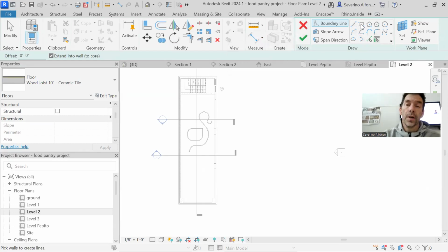But the drawing items, by the way, when you start a wall, when you start a floor, when you insert the door, the whole top bar changes, and it's a little bit confusing sometimes. What did you change my set of tools? Yes, I changed it. And at the beginning, you get a little annoyed, like, why are you doing that? Where am I? So just think of an editing mode or creation mode. It lives in a different kind of tab, so it just changes automatically when you do something.